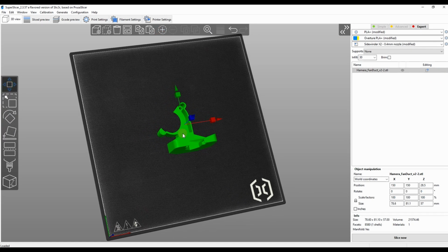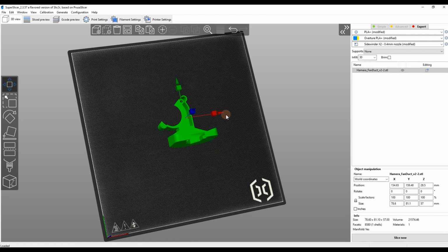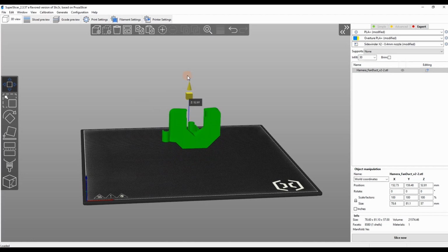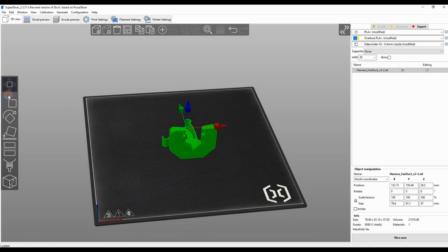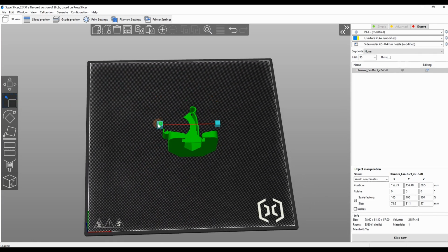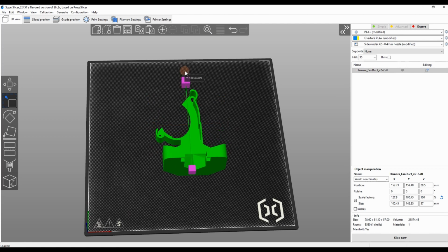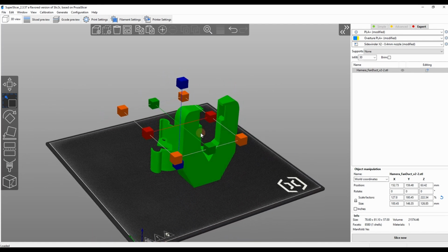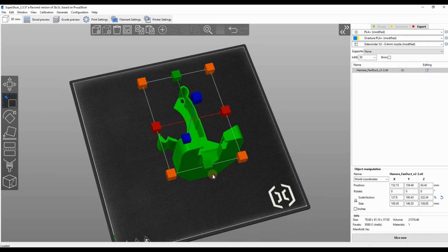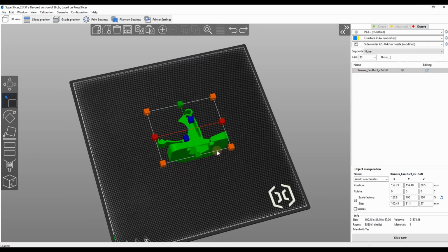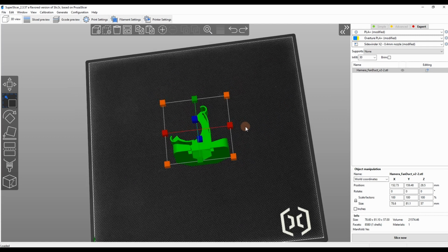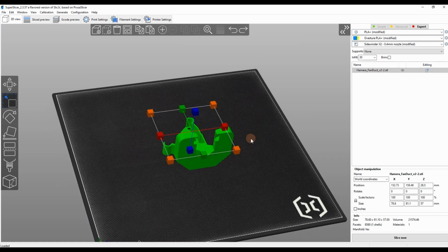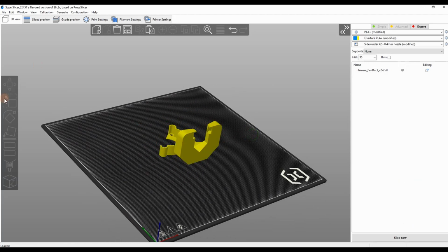So move, you can slide this all around. You can drag it with the arrows and the box. You can scale parts. Just be careful with that. It's going to throw off some of your dimensions if you have dimension things. Your walls won't be the same thickness, stuff like that. So I end up not really using that one much, especially for the type of stuff we're doing.